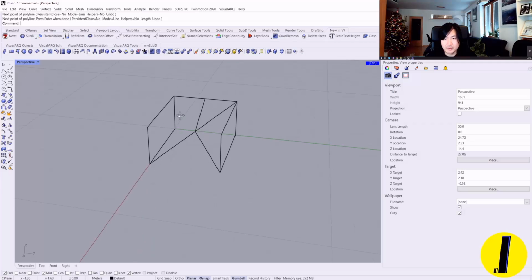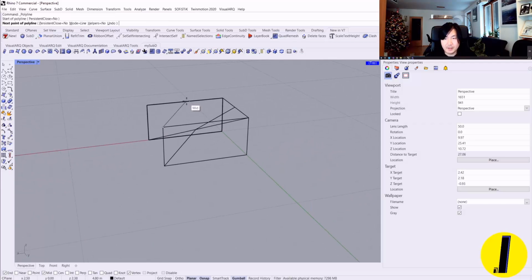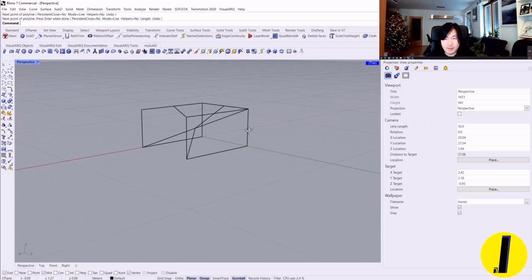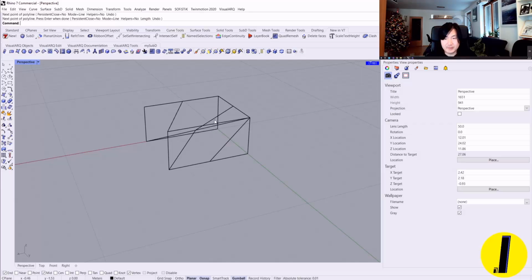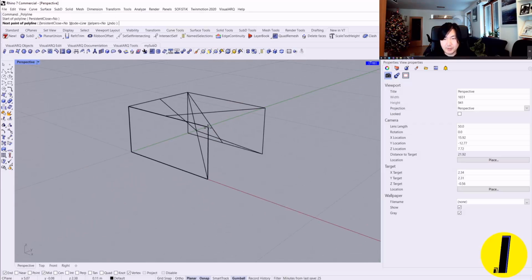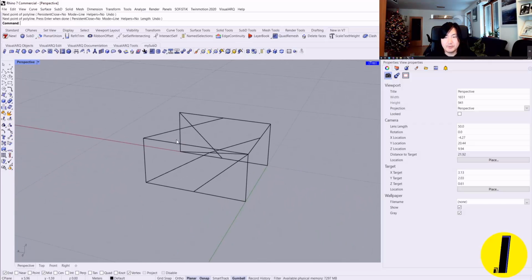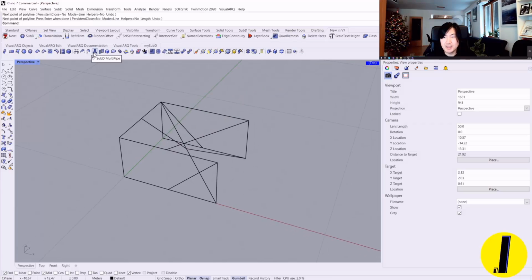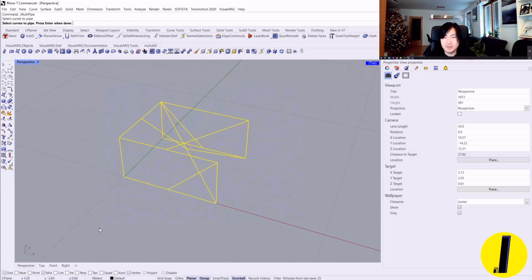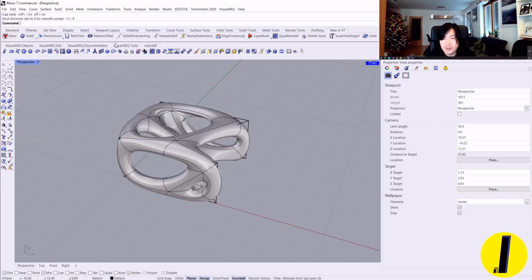Let me make it a little bit geometrically funny kind of network here. So let's say we have this sort of complex network of curves that we want to pipe with a subdivision pipe tool. The command is called multi-pipes, so SubD multi-pipes. We can click on that, and now I'll select all these curve lines, and for radius, let me make it maybe 35 centimeters, and we'll cap them. And if you set it to 0 for smooth curve, I'll make it 0, and let's have a look.